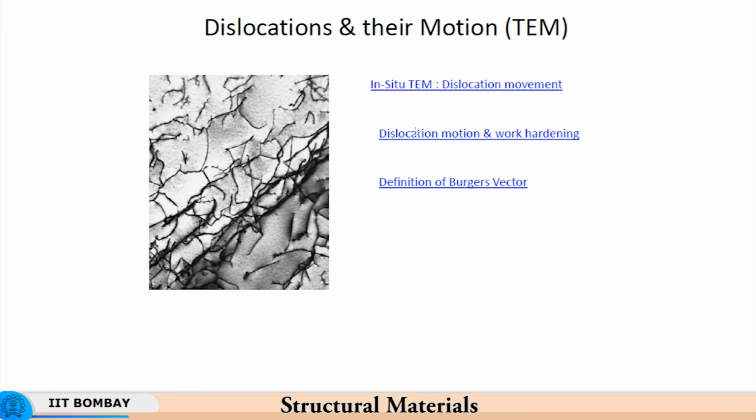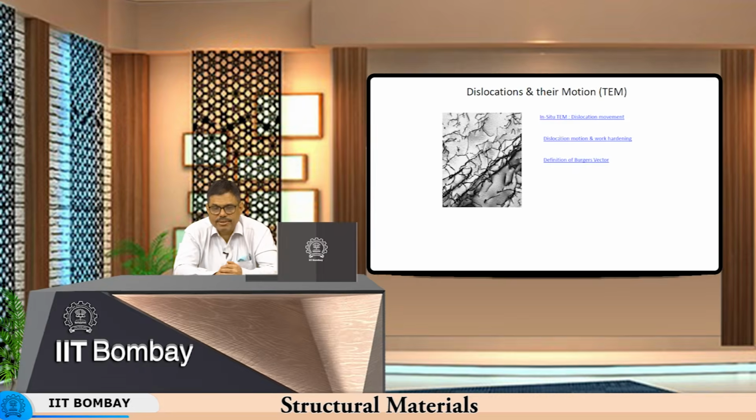That is what happens to a dislocation as well. When there is a large number of dislocations present on a plane, the dislocation movement gets hindered because of fellow dislocations present on the same plane. These interactions are similar to the interactions that happen with people moving through a crowded place.